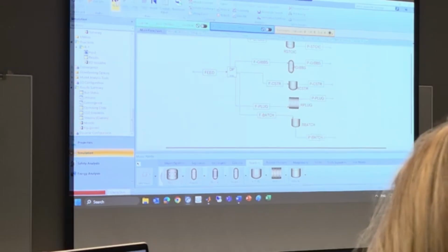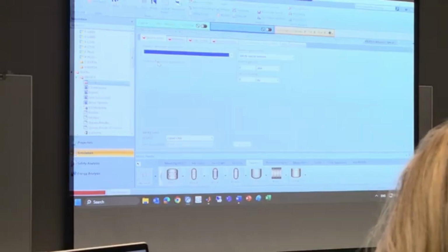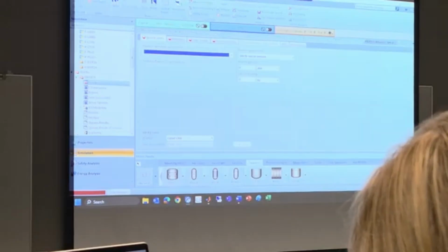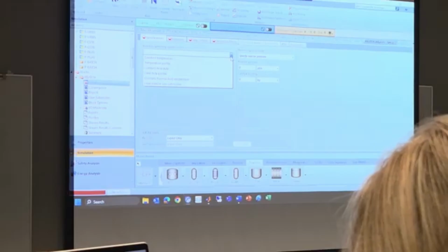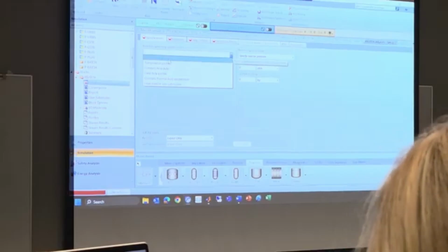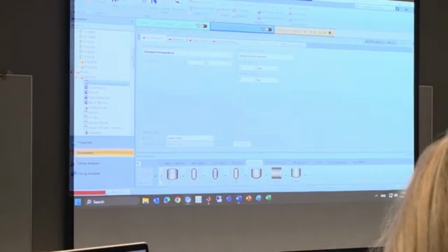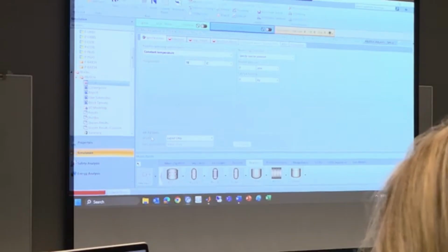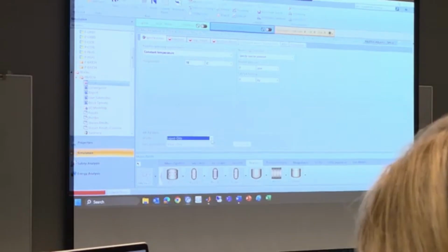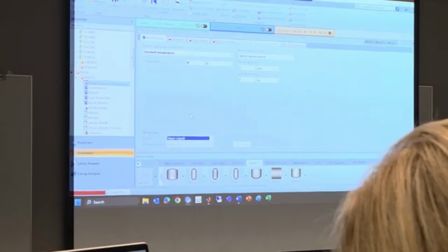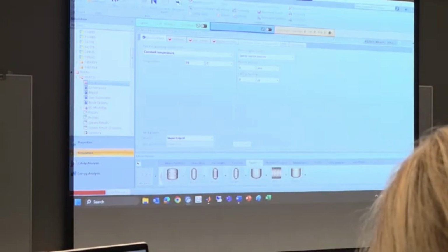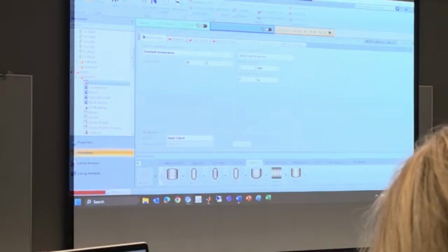Okay, so what is required? If you click next, specification: we are working on constant temperature, so I can choose constant temperature, 70 degrees Celsius. Valid phases, vapor-liquid; always check the valid phases. Pressure, given 1 atm.